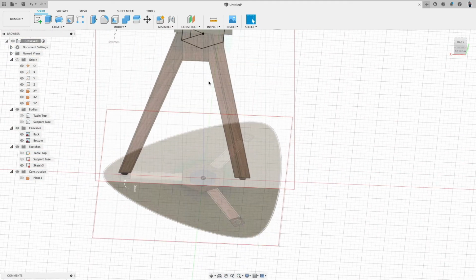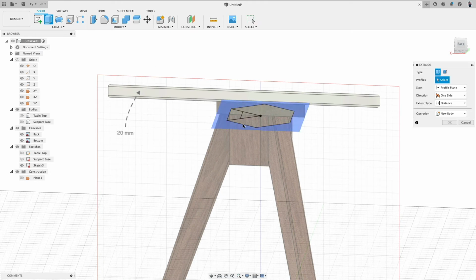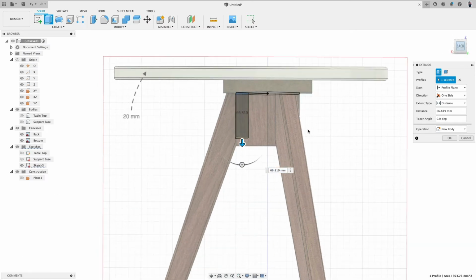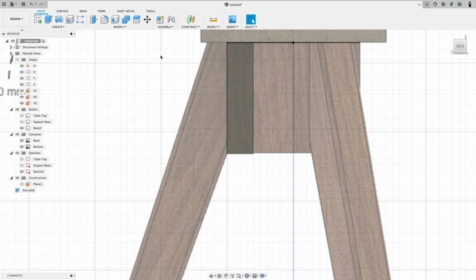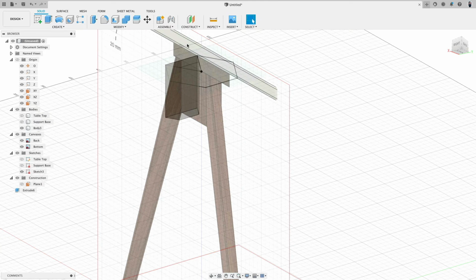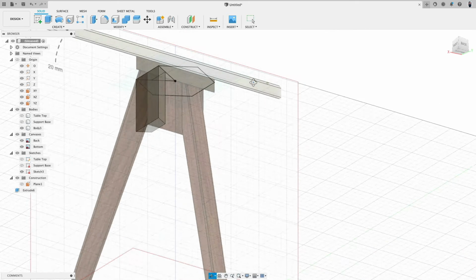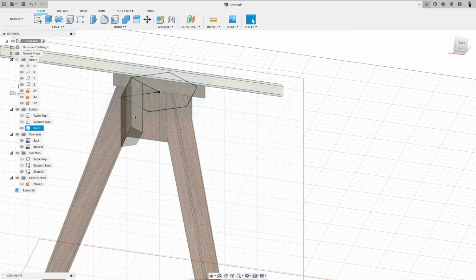So what I will do now is I will go to extrude. See, I have all these bodies not visible, and extrude this simply down to what length? Let's say 80. Yeah, oh, 80 looks good. 79. That's not very clean. In general, with dimensions, you can use whatever you want, but always be mindful about the person that later has to create everything. The easier the numbers, the more mistakes you can prevent when something is being produced. Very good. Now we have actually one piece.